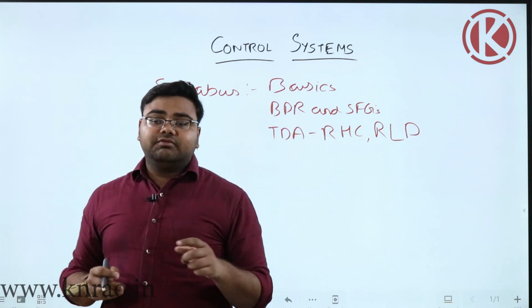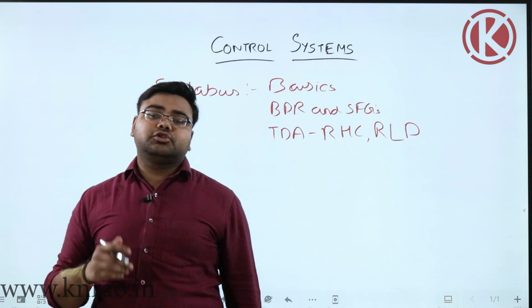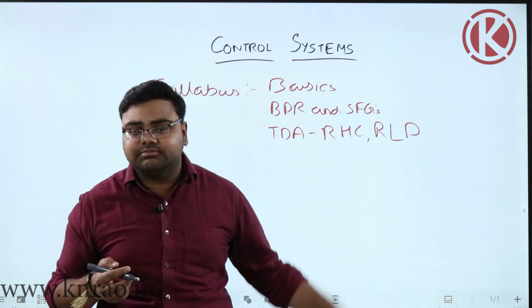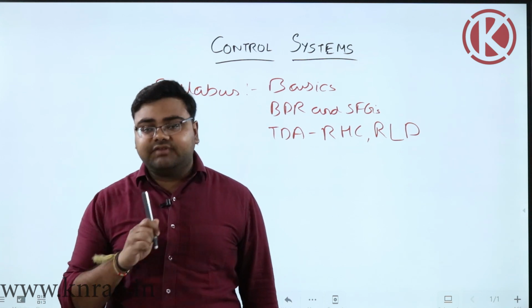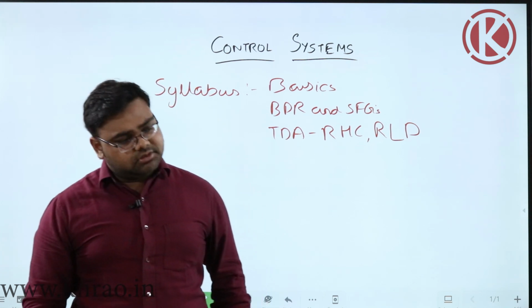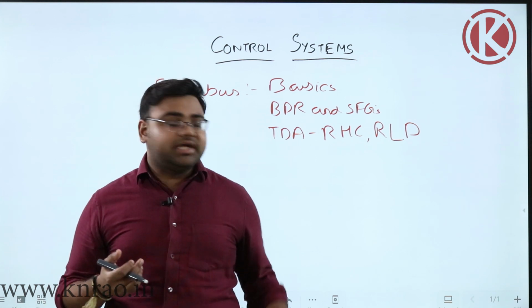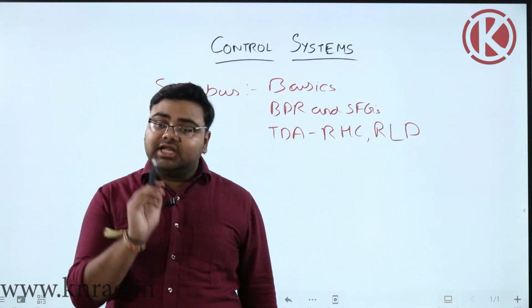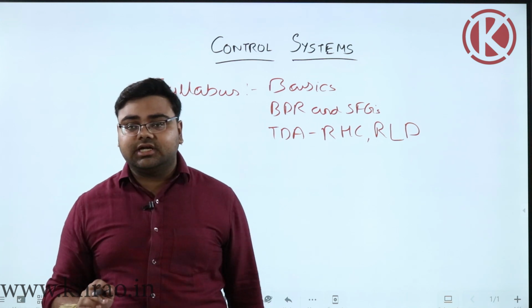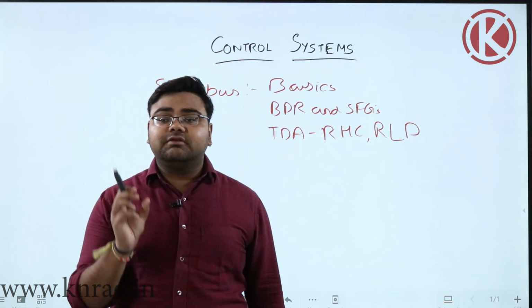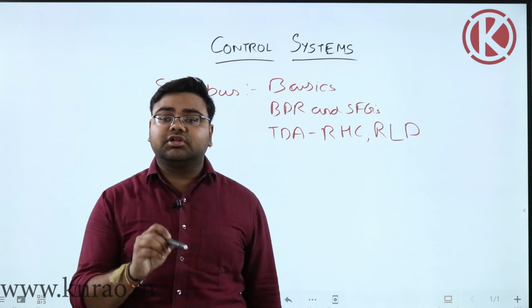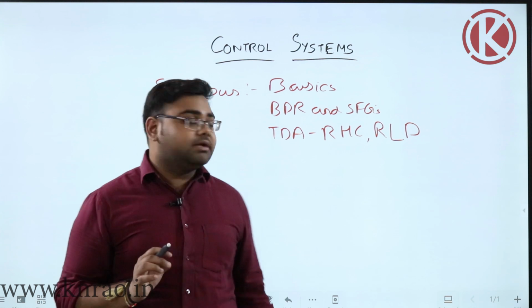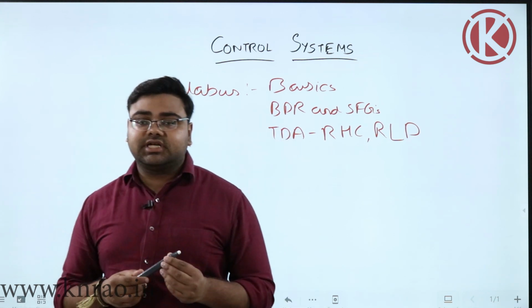And let me tell you one thing as to why the root locus plot is taught after Routh-Hurwitz criteria. Many people ask, can this be taught interchangeably? But no, you can't do that. Why can't you do that? Because there are parts in the root locus plot that can be found out only by applying Routh-Hurwitz criteria. And what is that? The critical value of k at which the root locus plot will cut the j omega axis, right? So that thing can only be analyzed using Routh-Hurwitz criteria.